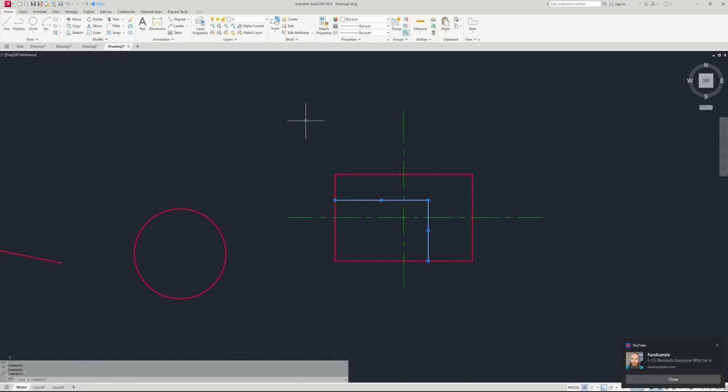Now every time you select the line, its layer type also gets displayed. Those two white lines are layer 0. So I can left click and then change the layer type to hidden. Okay, so I've seen my dashed lines hidden. Okay, let me attempt to dimension any of the objects.